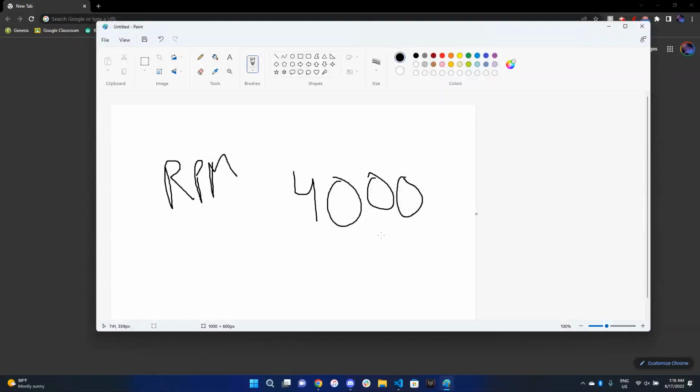So how fast are we going to get it? Because you can't directly actuate a Falcon motor at a specific velocity. Like there's no method that says, hey, spin at 4,000 RPM. Rather, we have to do some math ourselves and figure out, all right, are we getting at that RPM? And what can we do with this RPM? So that's pretty much what we're going to be doing today.